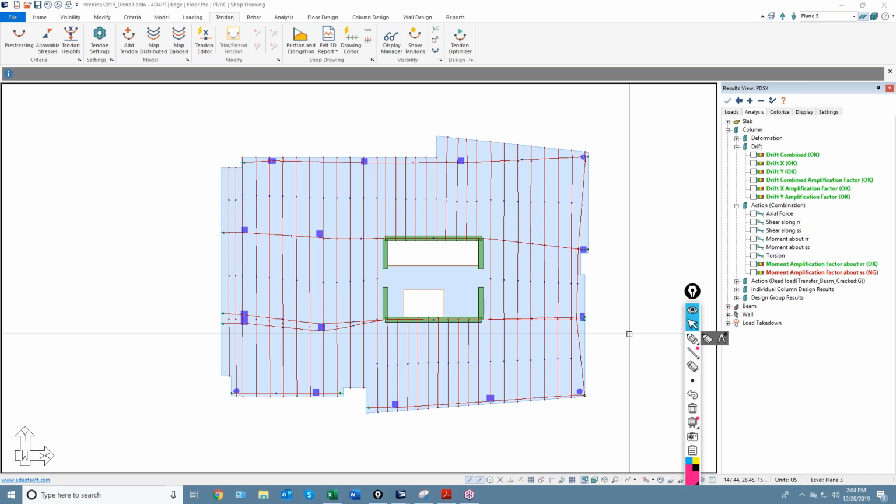The question is, do I recommend running the P-delta with a master combo? I would say yes. Typically, if you're going to be running P-delta, that would mean you're going to have a multi-story analysis anyway. For the most part, the geometric matrix is driven largely by the sustained load, the axial tension and compression forces in the vertical components. Those are affected somewhat by the lateral component, but not to a great extent typically.